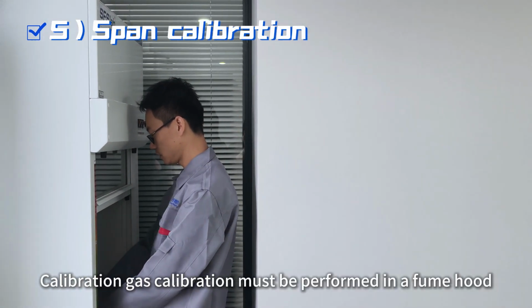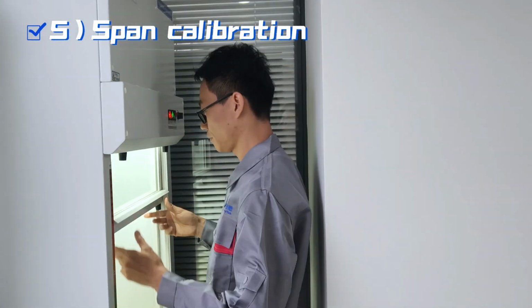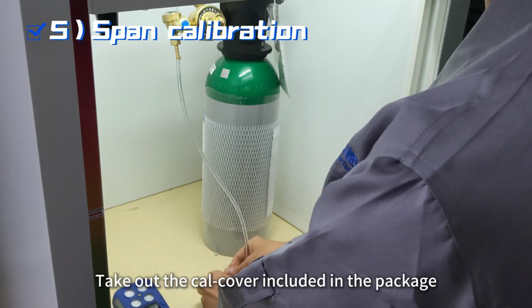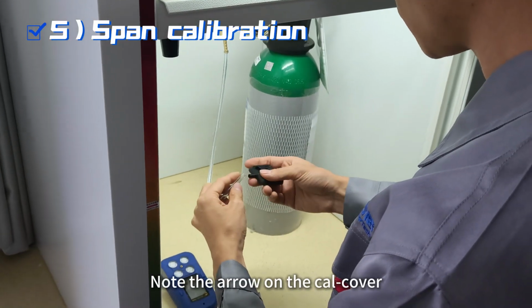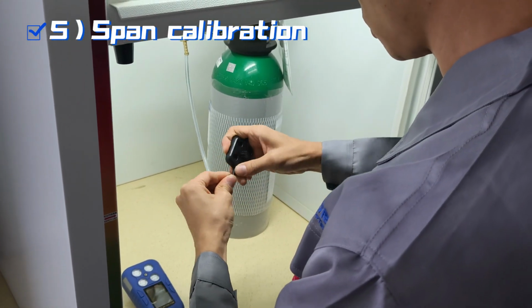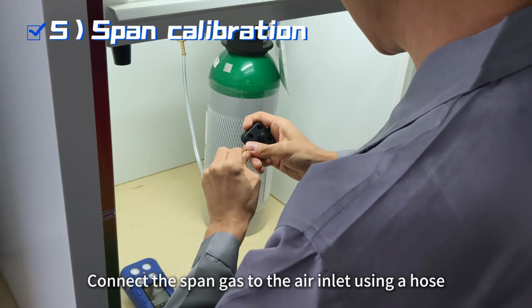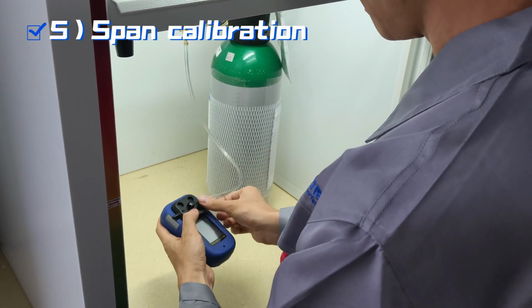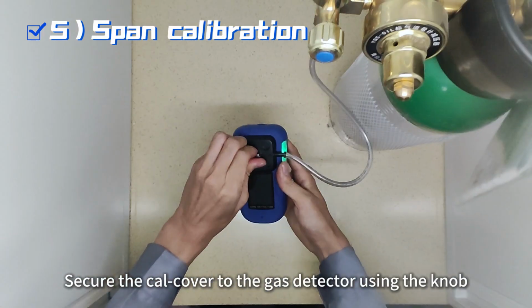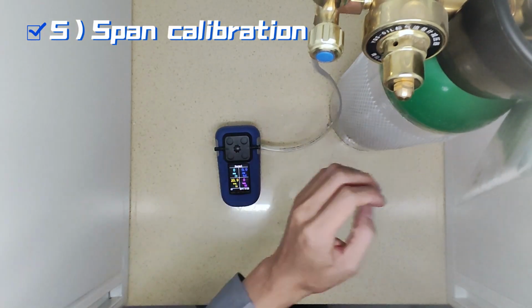Calibration gas calibration must be performed in a fume hood. Take out the cal cover included in the package and align it with the instrument interface. Note the arrow on the cal cover. Connect the span gas to the air inlet using a hose. The other side is used as an air vent. Secure the cal cover to the gas detector using the knob.